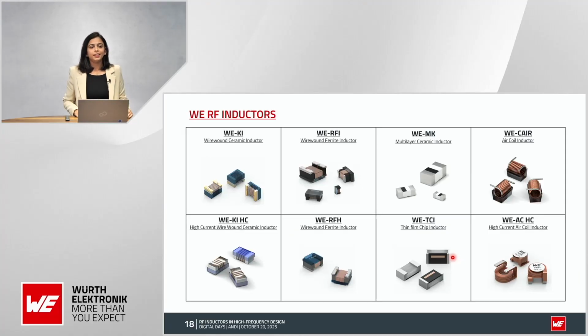Now let's take a look at the inductors that Würth offers in their portfolio of RF inductors. First come the wire wound ceramic inductors, which are WE-KI and WE-KI-HC. Then the wire wound ferrite inductors, WE-RFI and WE-RFH.